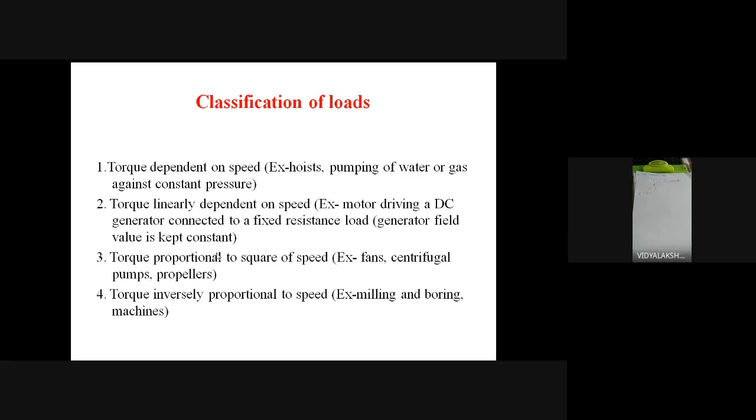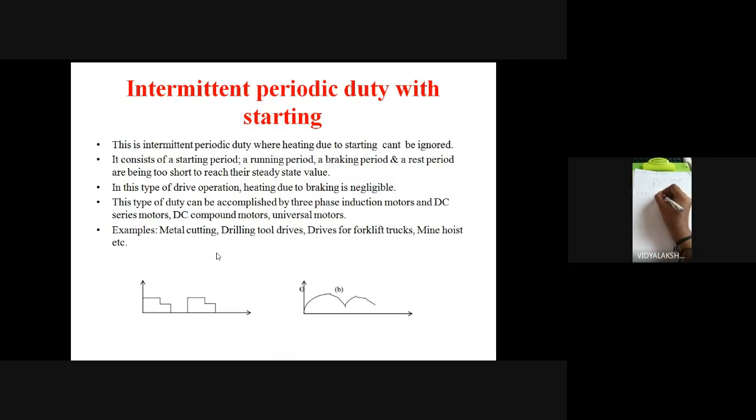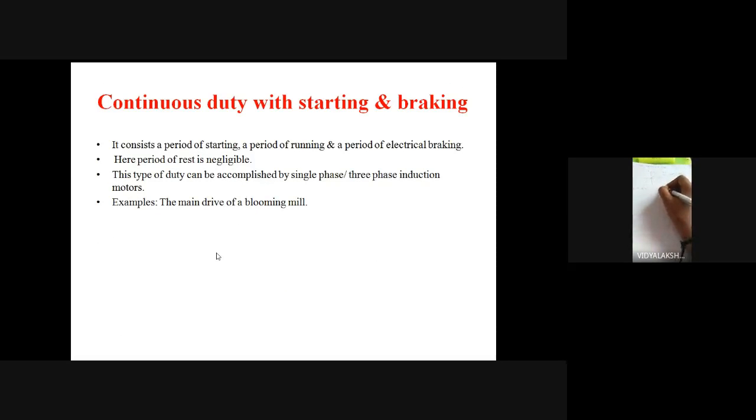What is torque? Anybody? Twisting force. Yes, twisting force. The same I have done in the regulator. If I'm twisting or rotating, my speed will be increasing. Here, in the fan type, the torque increases with the square of the speed. For example, if I increase the speed to 2, the torque will be 4 times. So 4 times it will be increasing.